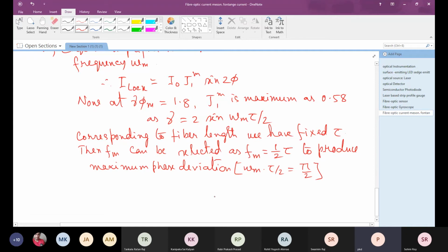So essentially that is to make the circular rotation the dominant factor in the optical fiber. And then the current produces a small amount of circular rotation, or the gyro also produces a small amount of circular rotation, so that is additive to that frozen circular rotation.